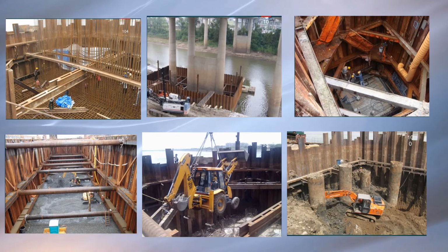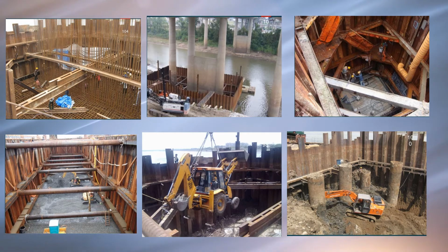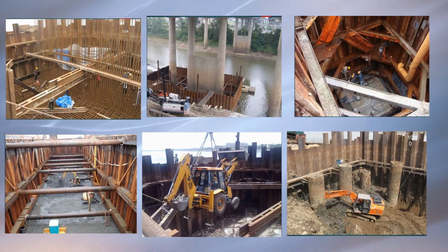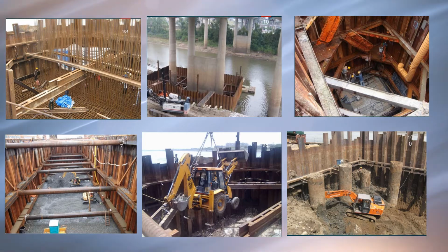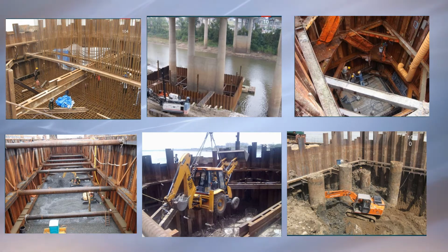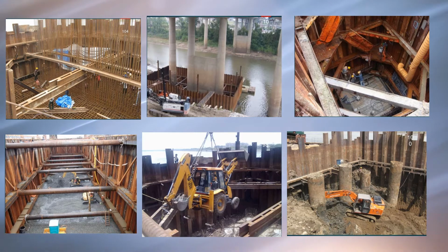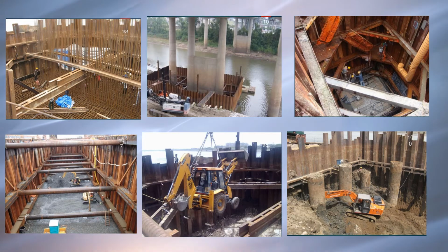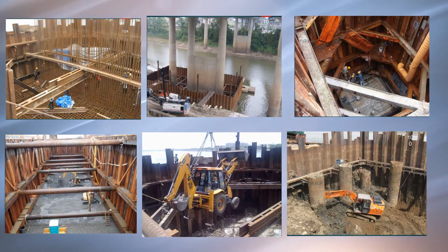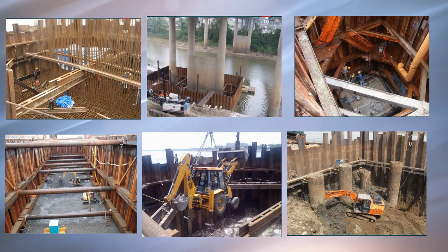The construction procedure includes driving timber sheets in the riverbed along the perimeter of the construction, within which steel piles are driven, maintaining equal distance using wales. The wales are bolted with connecting sheets on either side. To improve stability, cement bags or sandbags are put on both sides of the walls. After dewatering of the area, construction is executed.